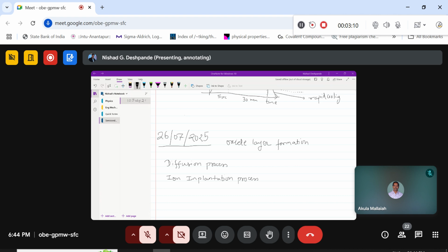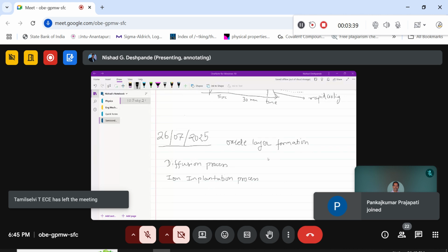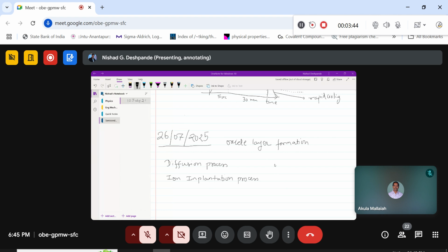We talked about this particular part where we were discussing how the reaction at the interface takes place. Thereby, there are diffusion processes that also occur, which help further to get the reaction and the diffusion processes to have an oxide layer on your surface. This is where we discussed how the diffusion kinetics, or the surface reactions and the chemical reactions, are more useful, and along the distances of the silicon wafer, how these processes are important at different regions.